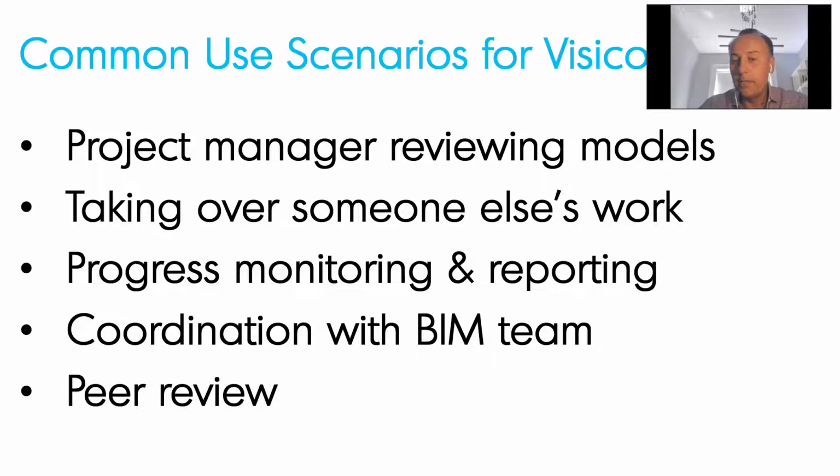Another common scenario is where you have one set of people who are building the ETABS models and maintaining them. You have a separate group that are creating the construction documentation in, let's say, Revit. And the question is, what's the most effective way for the engineering team to transfer the knowledge, member sizes, sections, and all those things from their ETABS models back to the BIM team without just relying simply on screenshots? And that's where Visicon comes in.